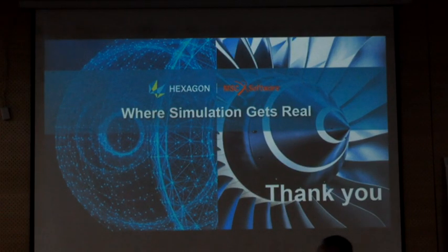One more thing is that, apart from generative design and topology optimization, this software can identify conformal cooling channels and part consolidation. That is thermal management, and that can be done, because many heat exchangers were 3D printed. We have done it. I have a live example with Bharat Forge. We have done that conformal cooling. And not only optimization: after printing, how do you ensure no powder or material is stuck inside a conformal cooling channel? That we have done. I have a case study, and I can share that.